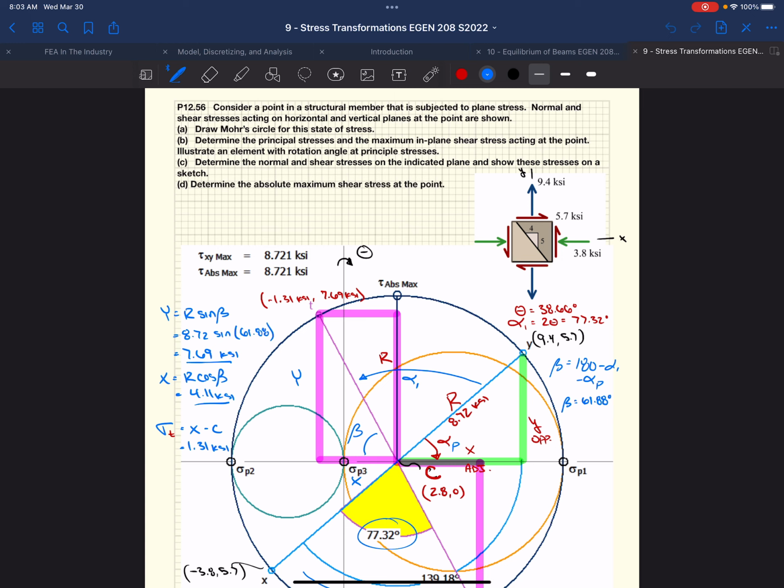Then when you start moving that point, say to find the principal stresses, in this case I rotated down to my sigma 1 and sigma 2. If I rotate clockwise and take my y point and move it to my principal stress 1, that means if I take this stress element and rotate it half that angle, then whatever my y face was before is going to be my sigma 1 in this case. And you would find the directions of that based on the coordinates.